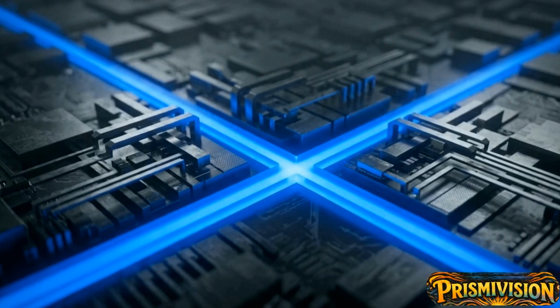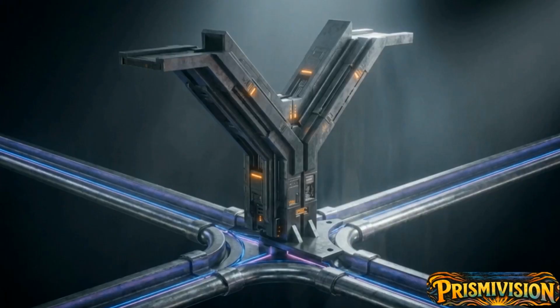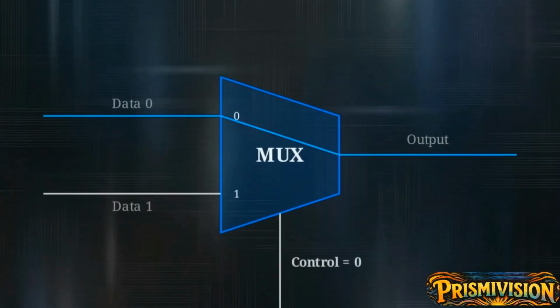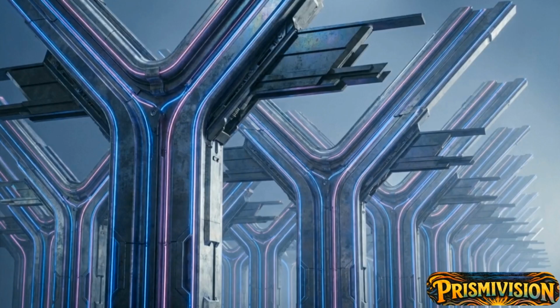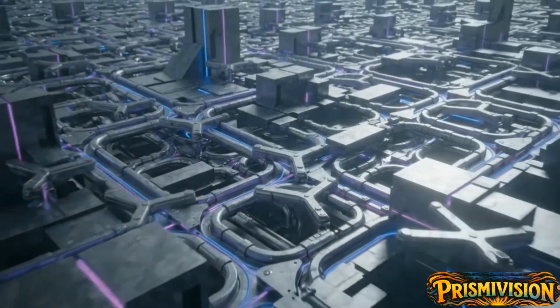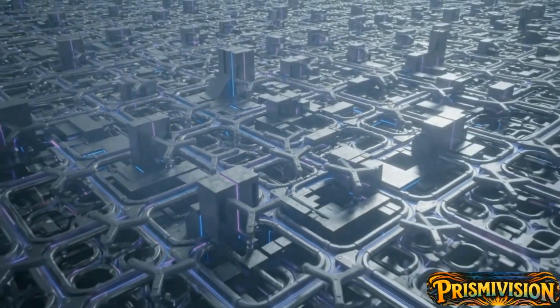As electrical data moves across the chip's buses, the paths are not straight lines. The signals frequently hit intersections where multiple routes are possible. Positioned right at these intersections are physical electronic steering gates, called multiplexers or data selectors. A multiplexer receives multiple data inputs from different sources, but it relies on a specific binary control signal to decide which single path is allowed to proceed forward. These multiplexers function as a dynamic switchboard, allowing the processor to rewire its own physical pathways in real time to meet the specific requirements of the instruction.